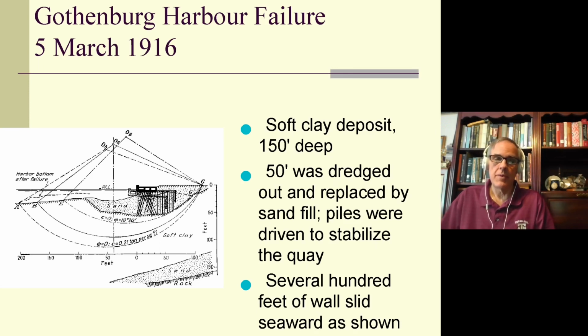And basically what happened was that a circular or semicircular segment of a circle failed, and a large mass of soil rotated around those O-shaped things at the top. And the elevation not only dropped, but the quay actually moved out into the harbor. And suddenly somebody realized that somebody else, or maybe even themselves, had not taken into consideration important things in the design of this.